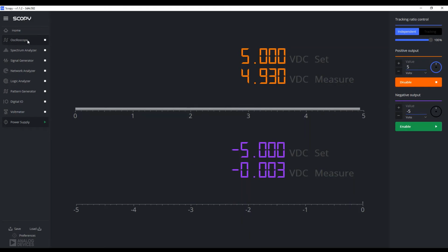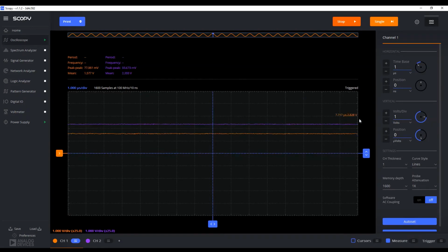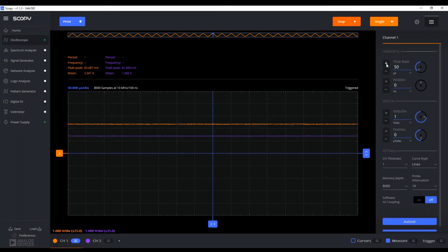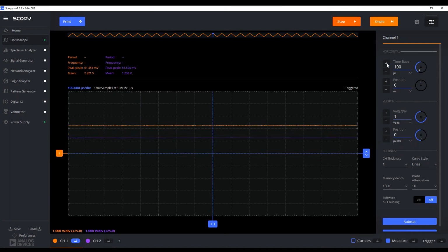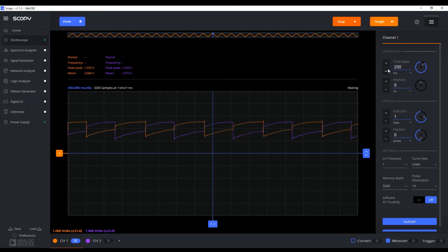All right, now we can go to our oscilloscope. Here I connected each of the channels into each of the LEDs in this multivibrator. So let's see what the, as you can see, it's oscillating, but we can better convey this by increasing our time axis. Right now it's incredibly small, 1 microsecond for each box of the grid, but because it's blinking in intervals of about half a second, if we increase it to 200 milliseconds, there you go.